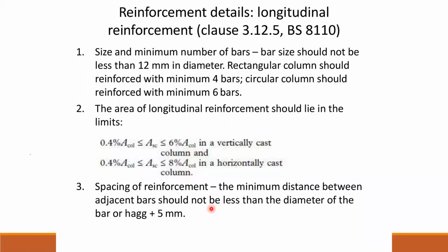Whatever designs you do based on the equation and the chart we referred to earlier, finally it should end up with these maximum values below 6%. Let's say the required reinforcement is greater than what is allowed in the columns as per the 6%. So what shall we do? The only way is to either increase the concrete grade, or else increase the geometrical properties. It means increasing the size of the columns would be highly effective.